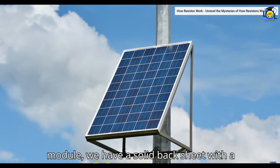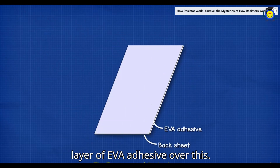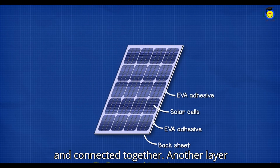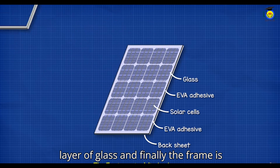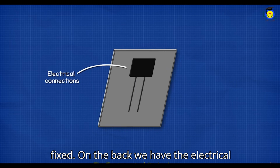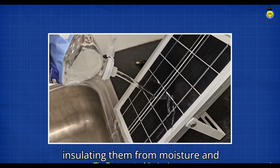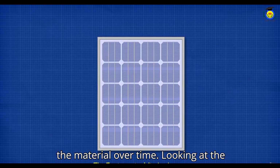To make a solar module, we have a solid back sheet with a layer of EVA adhesive over this. Then the solar cells are stuck to this and connected together. Another layer of EVA film sits on top of this, then a layer of glass, and finally the frame is fixed. On the back, we have the electrical connection which connects to the cells. The EVA encapsulates the solar cells, insulating them from moisture and mechanical stresses, which will degrade the material over time.